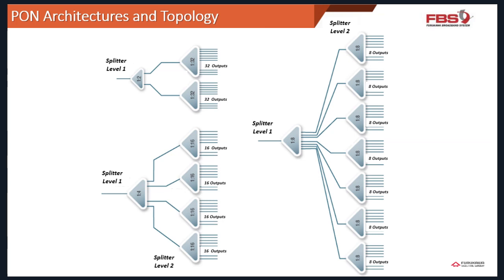So how you arrange that in a design depends on your network, the density of the customers, the take rate you intend to achieve. But generally speaking, the most useful and the most applied split ratio is 1 per 8 and 1 per 8 again. So you have the 64 here, as you can see on the right side. So first you divide by 1 per 8, and then again another 1 per 8. It allows you to spread your network through the area, right?